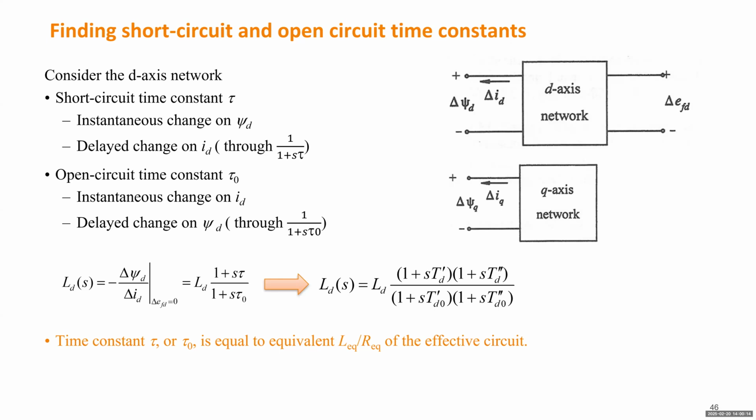Further, if we want to separate the transient dynamic from the subtransient dynamic, you have to add another order. Definitely, if you want to introduce an even faster dynamic than the subtransient dynamic, you put a triple prime. If you want to do that, you can. If your generator really presents that complex dynamic, you can keep adding orders forever. But typically, we only consider transient and subtransient dynamics, just two types of dynamics.